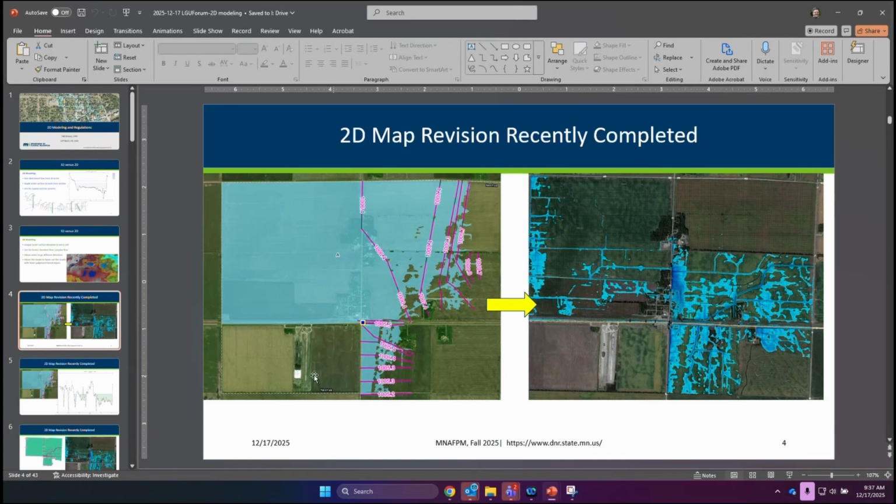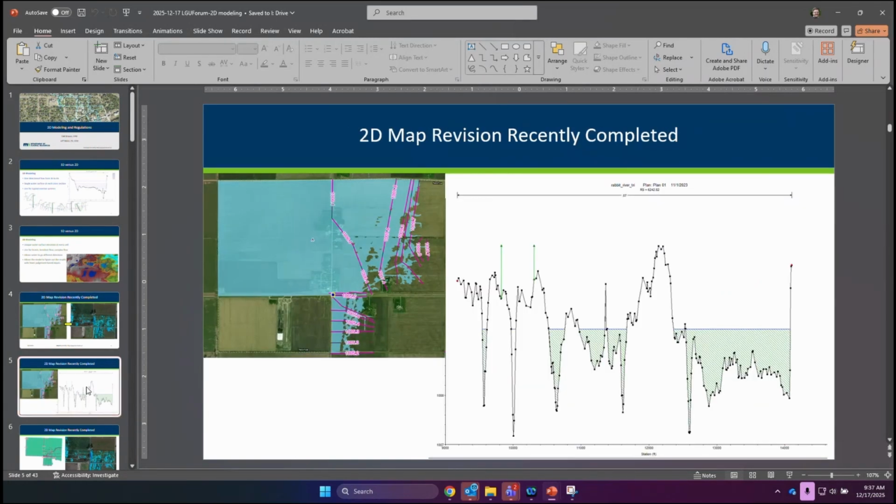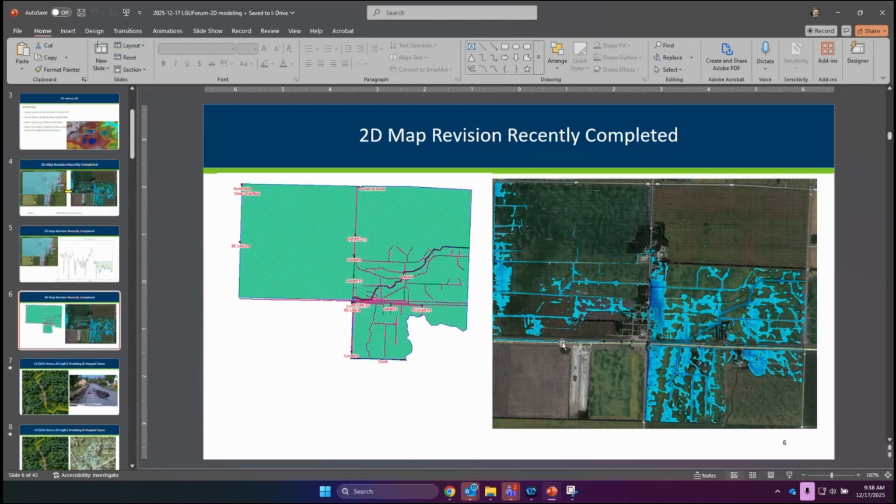And so, to provide a little more example here, again, the 1D modeling, this is a typical cross section that was coming out of here. Again, knew some water was spilling out over onto the right side, but the model, again, wasn't sophisticated enough to figure out exactly what that was going to be. Whereas with the 2D model, we were able to put in a terrain-based mesh, a LiDAR-based mesh, and put rainfall directly on it to compute the flows and figure out where the water was going.